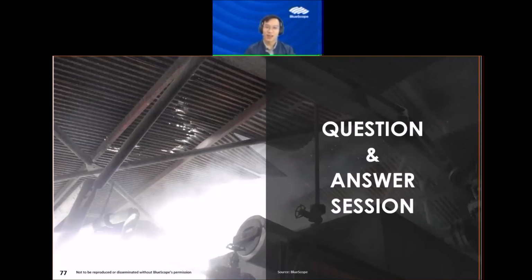Having the air out means something will come in also, right? So the air that comes in needs to be drier than the air going out. If the air coming in has a higher relative humidity than the air going out, then you're making the situation worse. So you have to consider the scenario here.